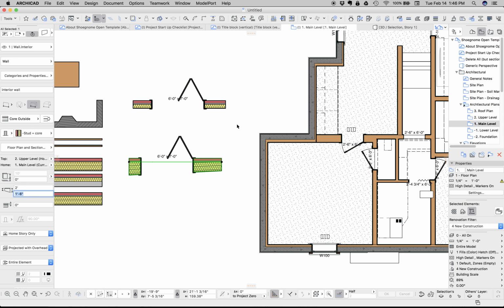The other place this gets into an issue is if you want, say, this to be the outside and this to be the inside of this wall, you might have to flip where the reference line is to get that to work. Why that matters is if you're doing a schedule and I want this door to open from this space into this space, this wall might need to be flipped back and forth.